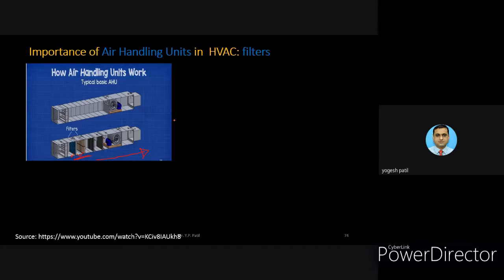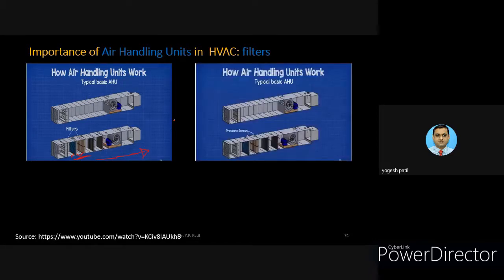Yes, that is also one of the things that is possible. So we want to remove as much of this dirt and dust as possible, right? That is possible by using filter banks, and some pressure sensors are mounted there. So it can be seen that across each of the filter banks, here there is a filter bank, and here there is a filter bank, there are pressure sensors.